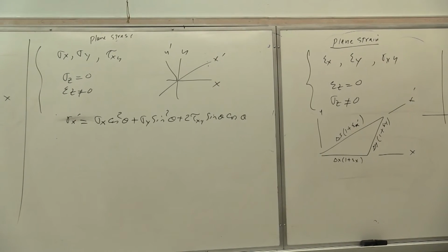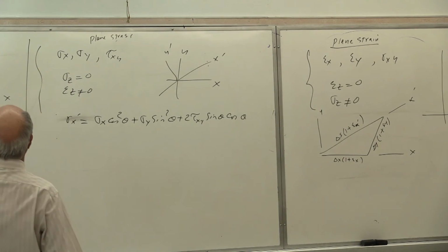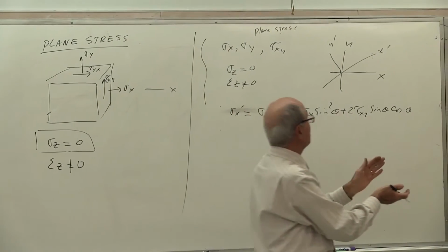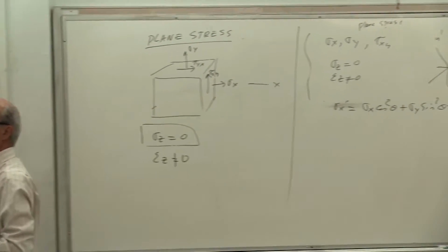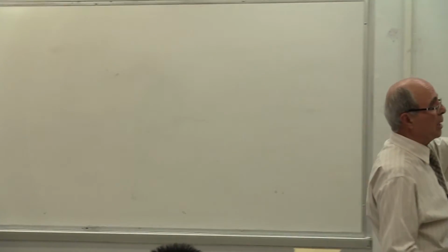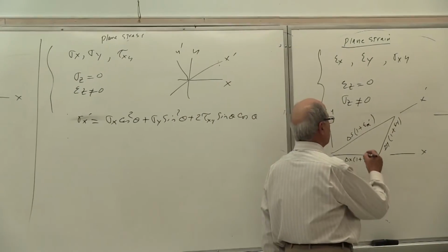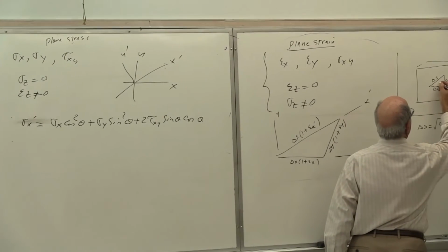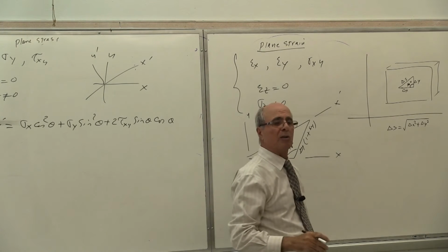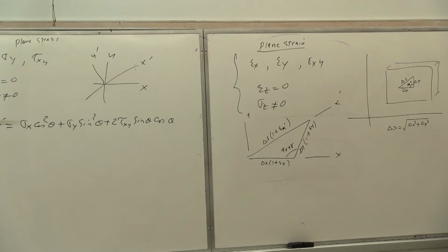Yes? Correct. What happened to that angle now? Why is that angle changing? Because of the tau. Because the tau causes the angular deformation. The angular deformation is what? The angular deformation is gamma. Yes or no? Therefore, I'm assuming all positive. This is not always the case. This is for proof of the formula. This angle was originally 90 degrees. Now it's becoming how much? 90 plus gamma. Although gamma is very small, and we have done some homework in ME 218 like that to calculate the value of gamma.